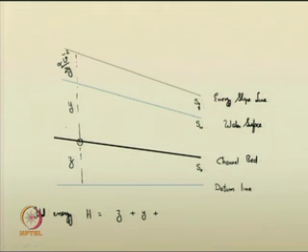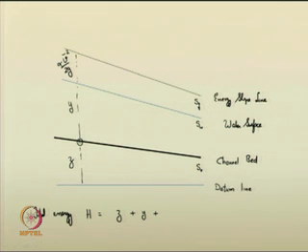Please note why it is the elevation of water. We are dealing with flow in open channels where the pressure is in hydrostatic condition. So, you have to note that we are not dealing with very high speed flows in such situations where you cannot use the hydrostatic assumptions. So, H is equal to z plus y plus alpha v squared by 2g. This is the general total energy head equation you have already studied.